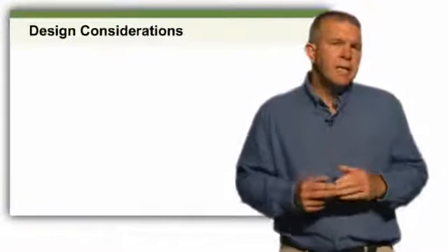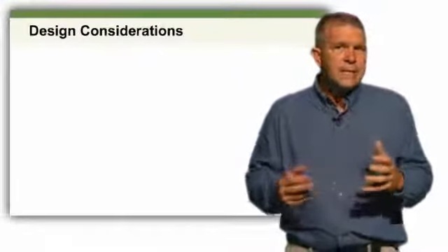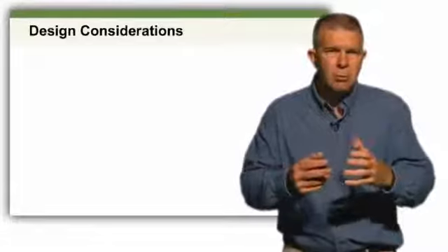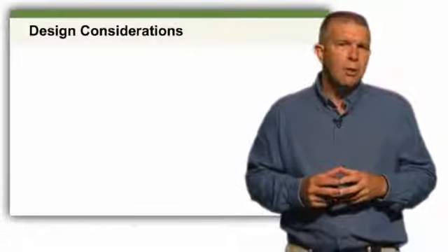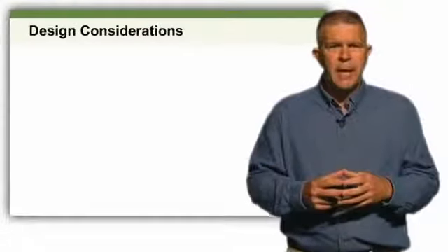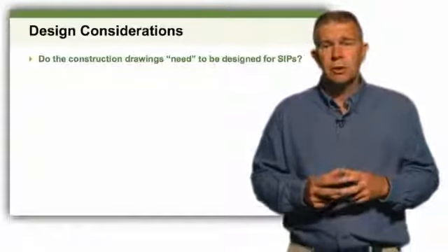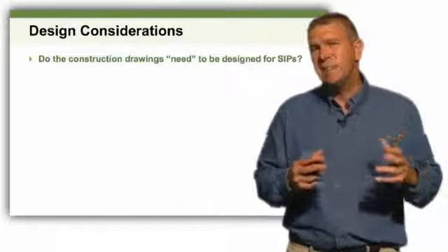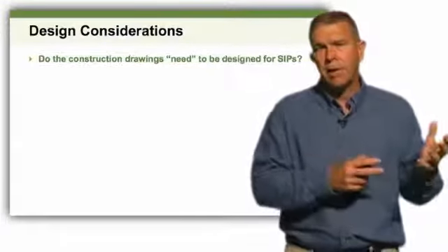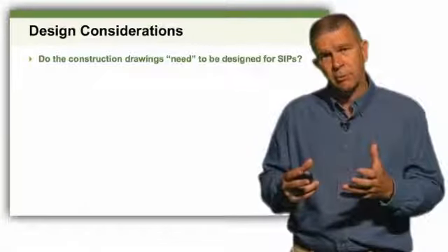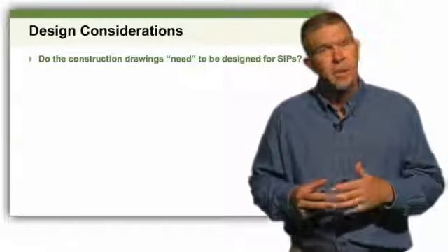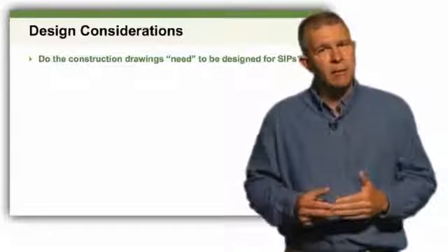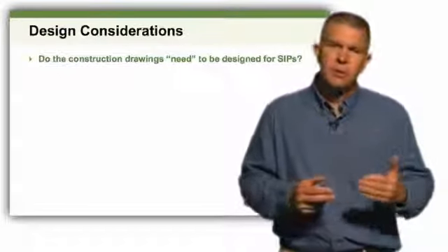There are certain design considerations that you need to think about when you start working with a complete SIP package. First and foremost: do our construction drawings need to be designed for SIPs? The architect may have designed a building, but not necessarily designed it for SIPs. That doesn't mean it can't be converted to SIPs, and that's where the designer steps in.